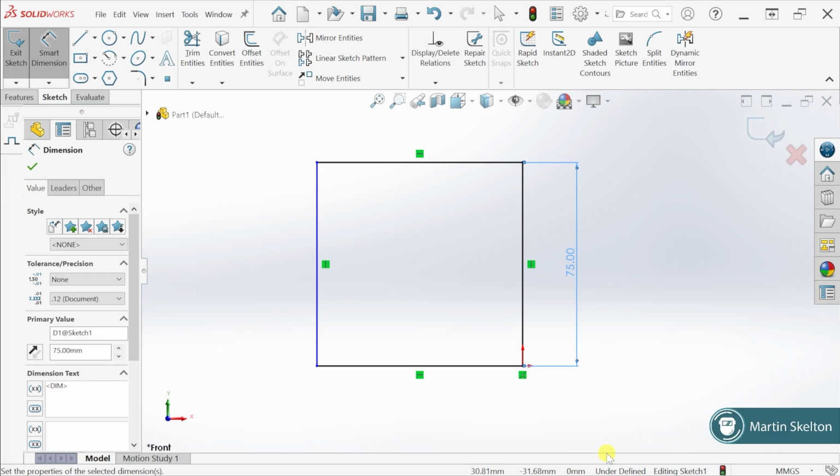We can add and take material away from sketches that are not fully defined, but you run risks. The risk is that the sketch will move and you lose vital, important or precise information. If you are sending something to manufacture, it is stressful enough to know that you have done everything correct and it gets manufactured correct.